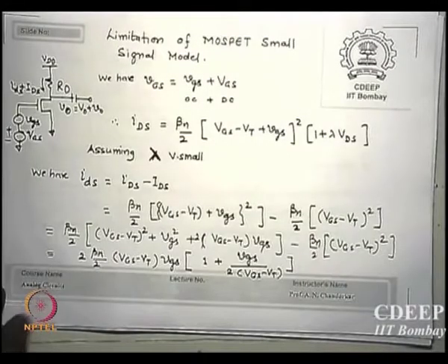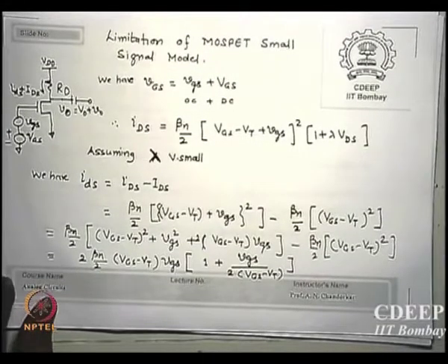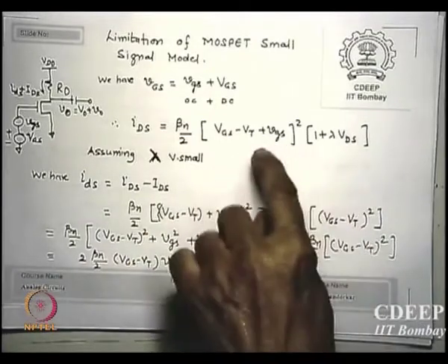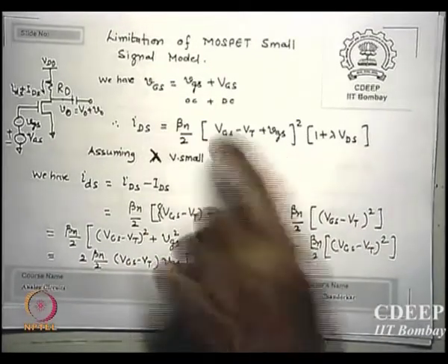Here we can exceed a little, but the problem is that gm is much lower, so gm vgs will not be larger than bipolar either way. So that is where the issues are, why bipolar and why MOS. I agree with you, but what I did was substitute the linear voltage part there.